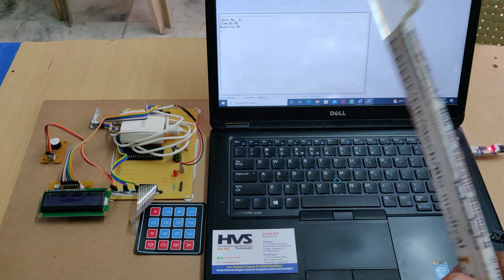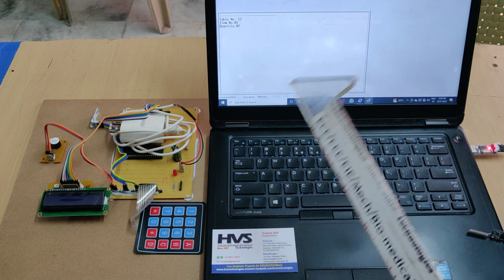In real time we can place an LCD or keypad based on availability. For wireless communication we are making use of Zigbee. There is a Zigbee transmitter and a Zigbee receiver. The distance between these two can work up to 100 meters and a maximum of 500 meters, based on the area, meaning based on the surroundings.